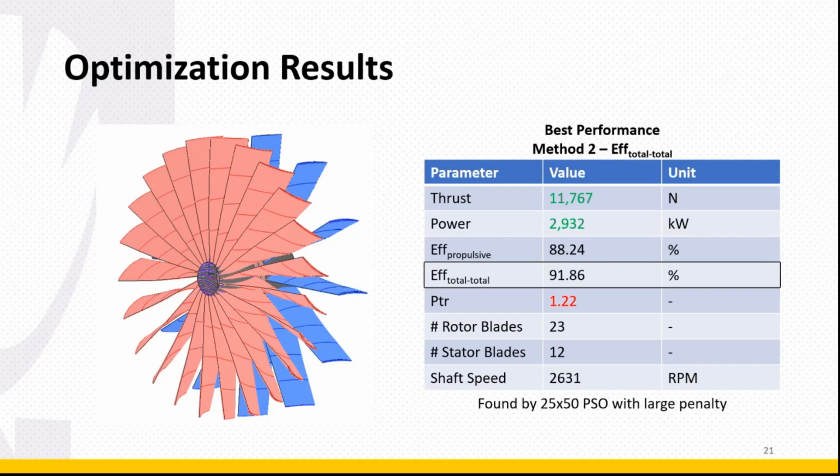This comes from the fact that the thrust constraint that I implemented in there is relatively large. The plus or minus 10% seems to be just a bit too large. Though I imagine if this were constrained to maybe plus or minus 5% or plus or minus 1%, we would see that total pressure ratio rise to meet the 1.25 that's required from the steady state model.